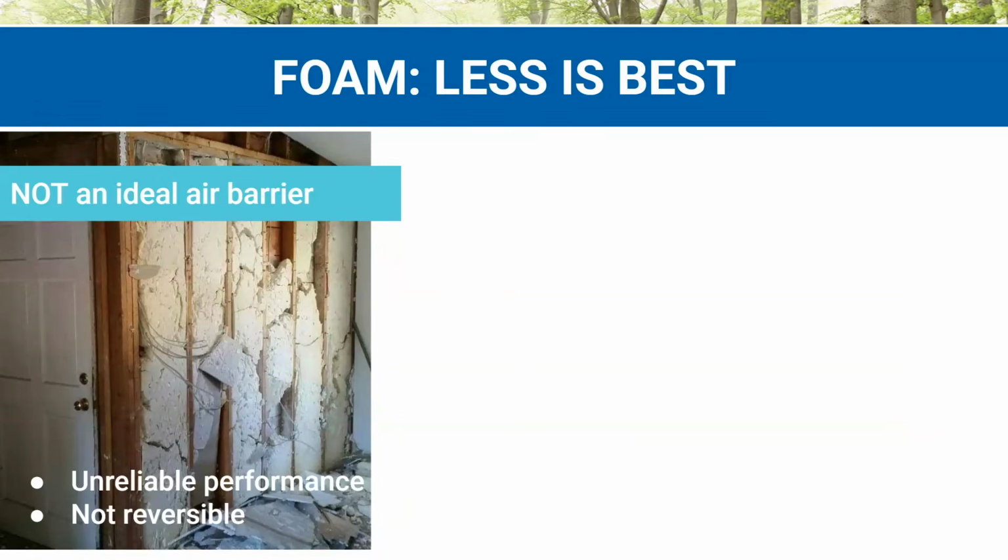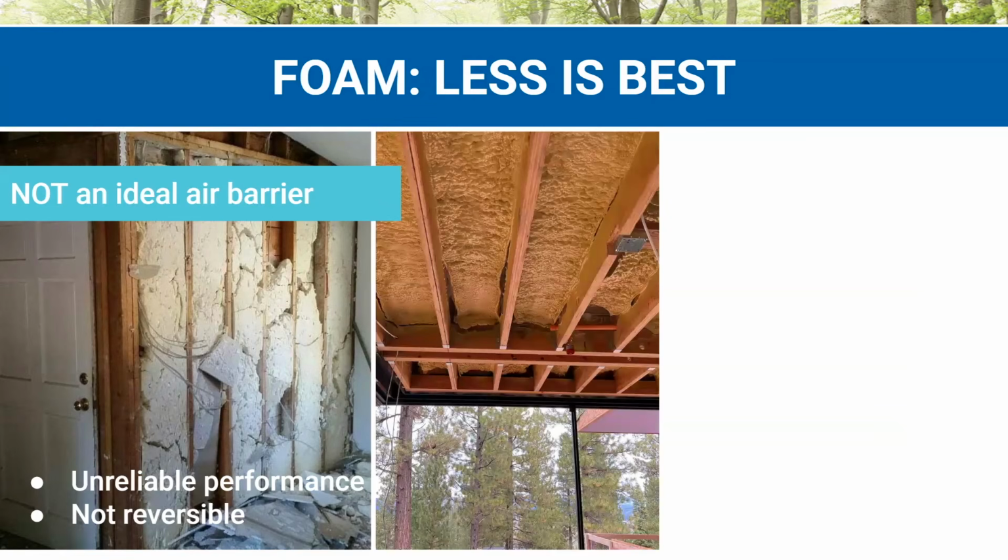Again, just speaking more to foam, spray foam is not a good air barrier. The material itself is airtight, but it's installed discontinuously, so you'll have air leaks at each stud. And again, the studs are going to expand and contract based on that moisture content. So it's not necessarily that this foam is shrinking off of these floor joists that we're seeing, but the floor joists could just be swelling in the summer because of the high moisture content and then changing shape a little bit in the winter. As it dries, it shrinks a little bit, and that's how we get these voids and cracks.